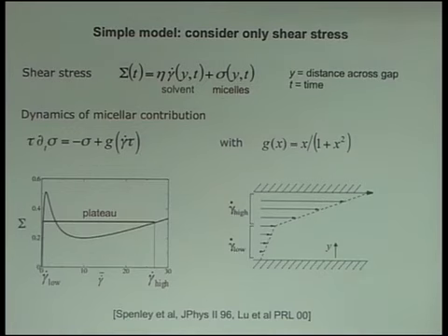And then there's one little mental switch that we need to make also, in thinking about shear banded flows. If you think actually what's going on here, if we plot the shear rate as a function of position across the gap from low to high, we've got a low shear and a high shear. And in the model as I wrote it down originally, there's no spatial structure in that. The streamlines don't communicate with each other, and there's nothing to tell that shear rate how to transition from a low to a high value. So actually in that model as I wrote it down before, there would be a step discontinuity in the shear rate across the interface. And actually associated with that, this plateau value of the stress would not be uniquely selected.